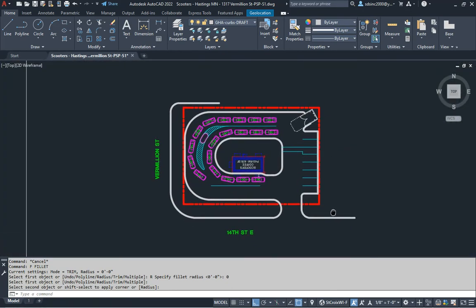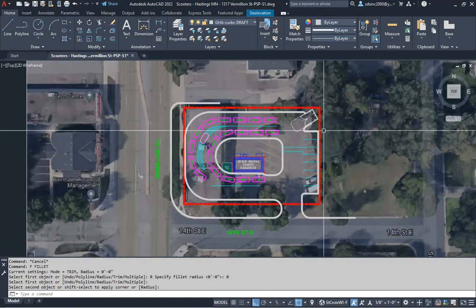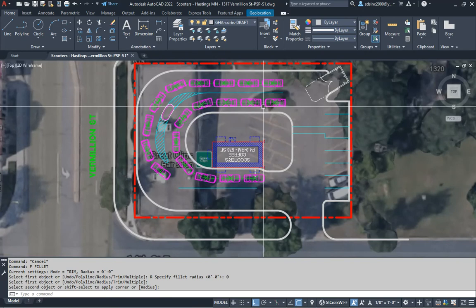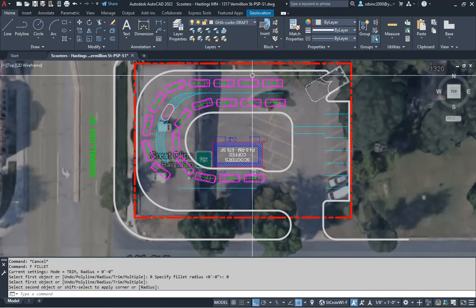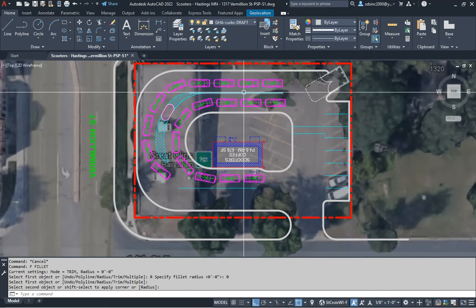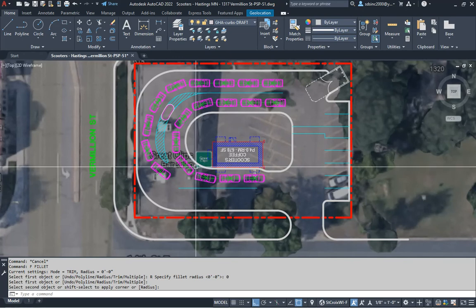And that is a pretty good block out right there, I think. It's got everything that we need. We got our service yard in there. Got the full stacking lane. Typically, for a stacking lane, we want 14 feet for these. We want to maintain 20-foot radiuses in the drive-through.